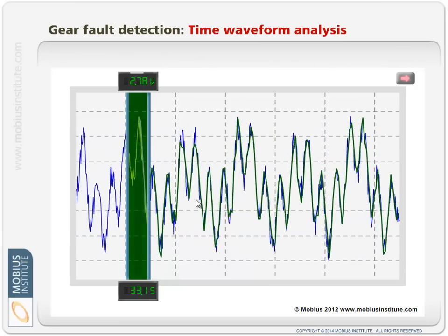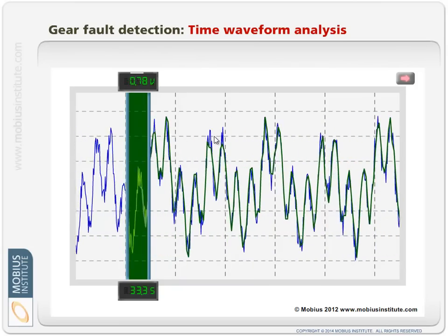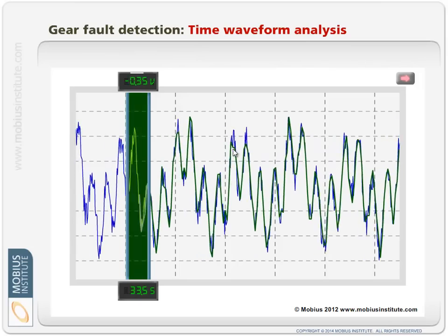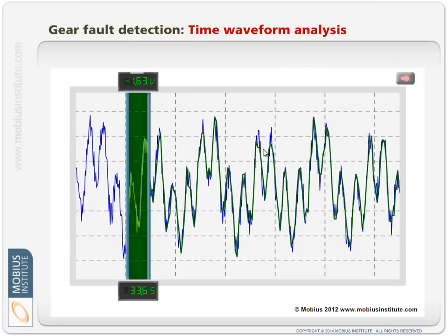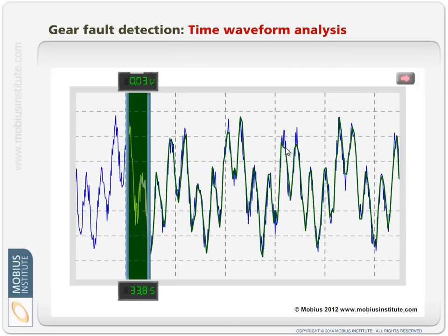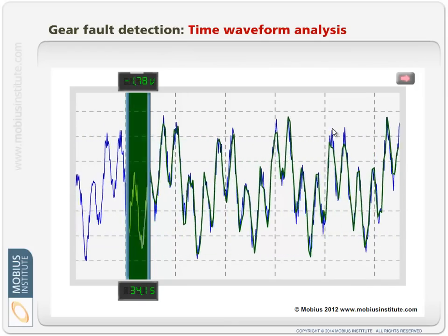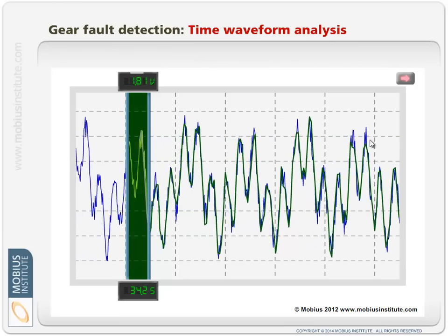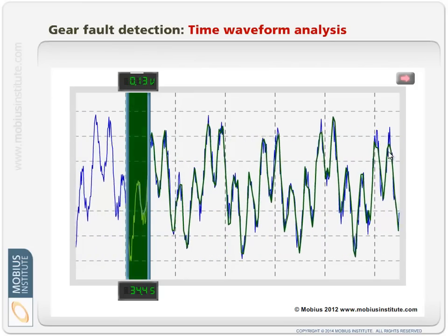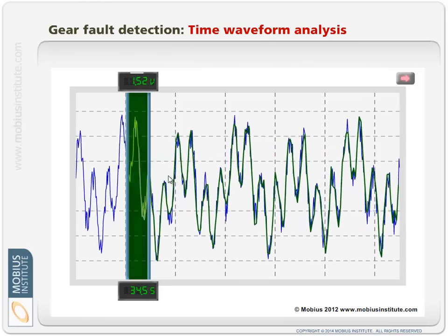I can't illustrate that easily, but if you look here, you'll see just here that there's a blue spike that goes up, but we didn't capture that. The green captured waveform is lower. We ideally wanted to get a digital sample up top here. You can see it there as well. We didn't capture these spikes. We sampled, even now we're sampling too slowly.